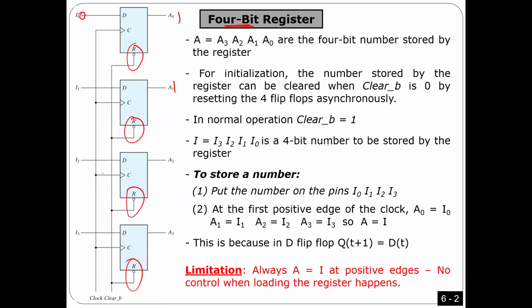So that's what I'm telling you. In the exam, if I ask you about this part, I will tell you to please draw a 3-bit, 5-bit, or 6-bit register. It's very easy to extend. This one is 4 bits. If I ask you to make it 2 bits, you stop here. If I ask for 3 bits, it's going to be here. If I ask for 5 bits, you add 1 more flip-flop. It's not difficult. Nothing is new, right? I'm just using D flip-flops.